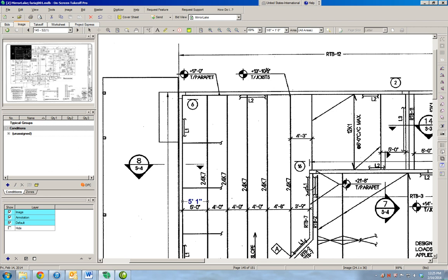This is 13.1 pounds per linear foot, so it's heavier than the 24K6. We'll use the 24K10 for the purpose of our estimate. So we'll be using $8.5 per linear foot in material, 1.43 in labor, and 0.73 in equipment. Of course, these are heavy joists that need to be moved with a crane and put in place. So that's why the cost of the equipment is a little bit high.